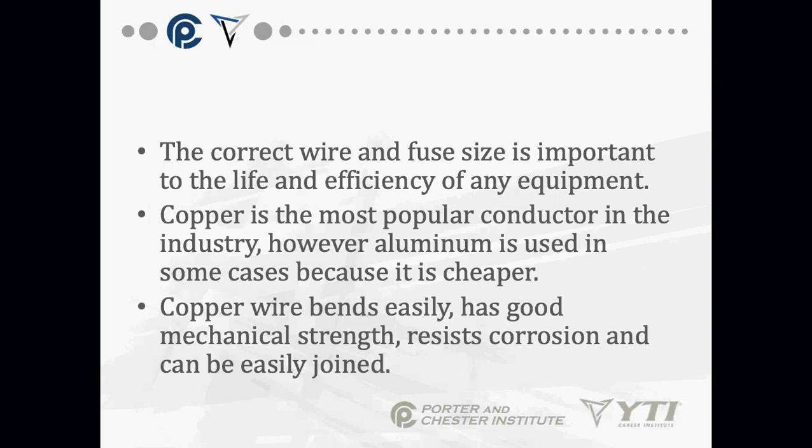In other words, if you're installing a furnace or an air handler in a basement or attic and you come across aluminum wiring, an electrician is going to have to update that branch. They cannot just install a new piece of equipment onto a branch with aluminum wiring. And that's most states. I don't know anybody that's now allowing new equipment on aluminum wiring. It's a problem.